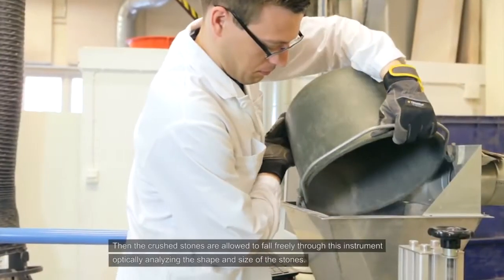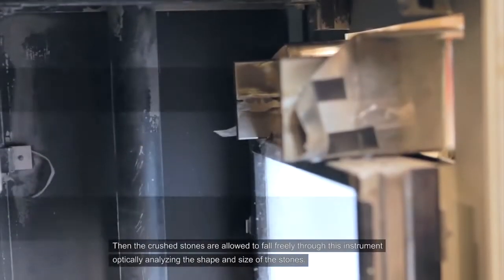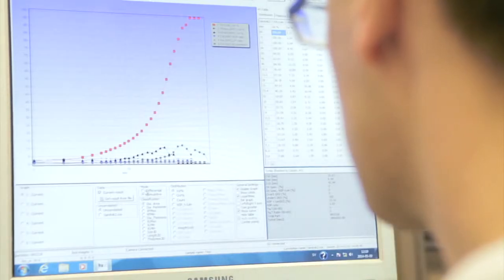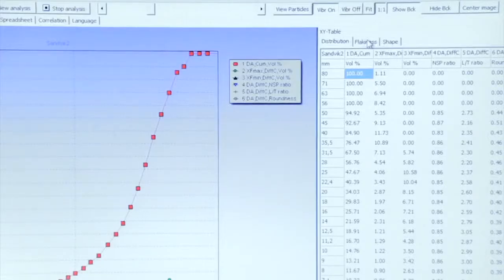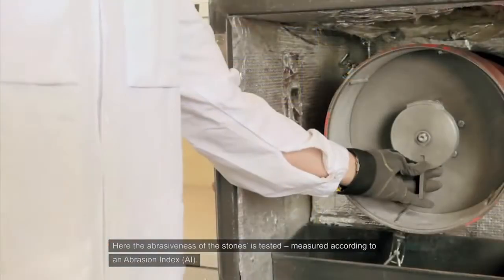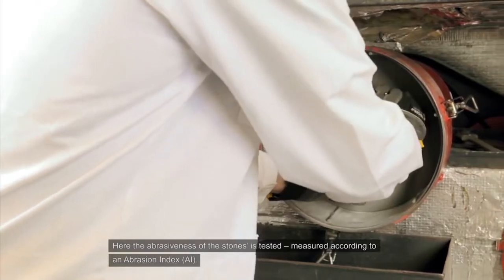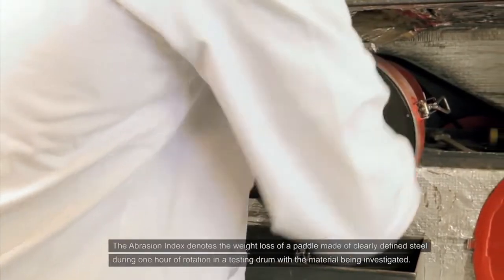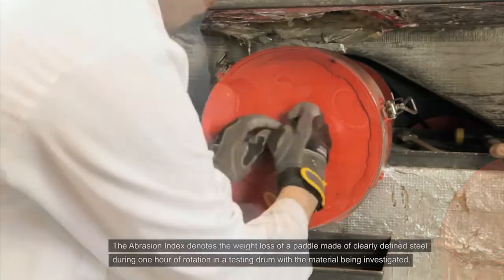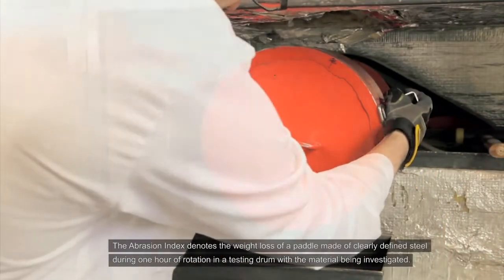Then the crushed stones are allowed to fall freely through this instrument, optically analyzing the shape and the size of the stones. Here, the abrasiveness of the stones is tested, measured according to an abrasion index. The abrasion index denotes the weight loss of a paddle made of clearly defined steel during 1 hour of rotation in a testing drum with the material being investigated.